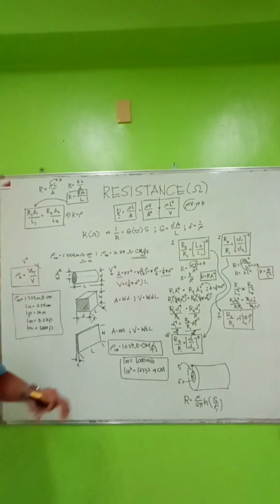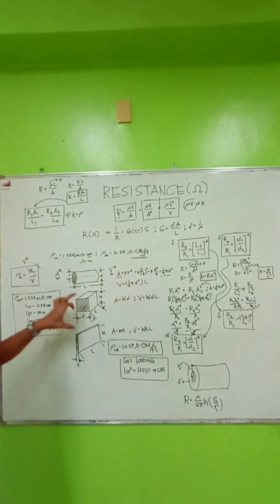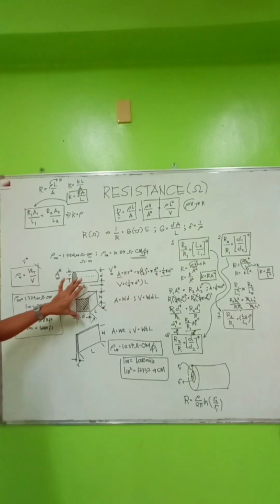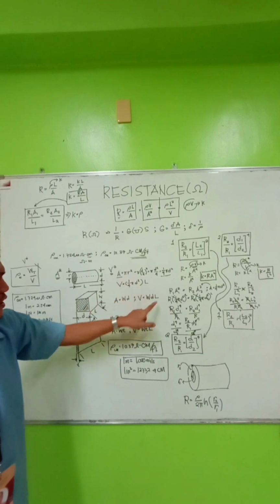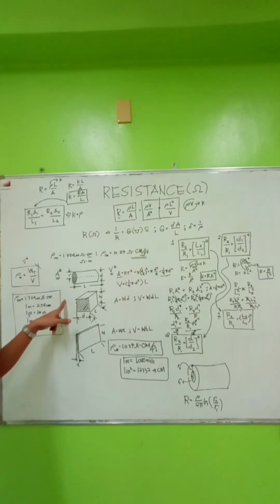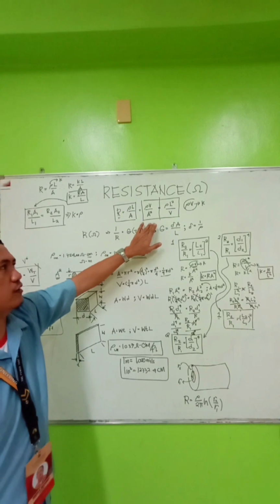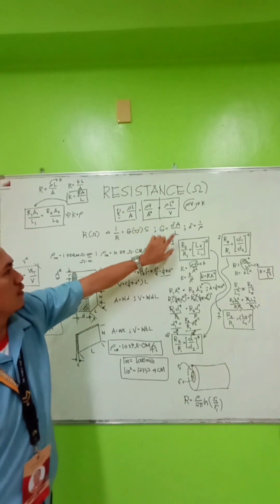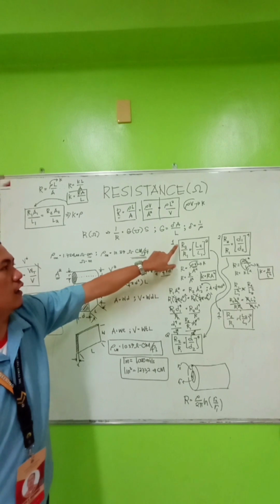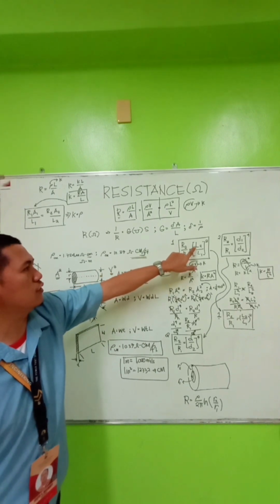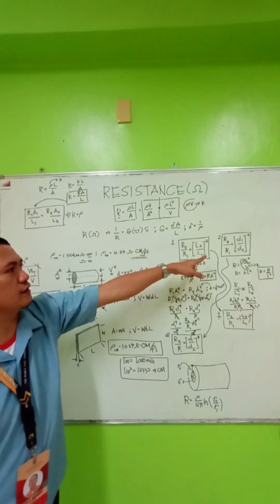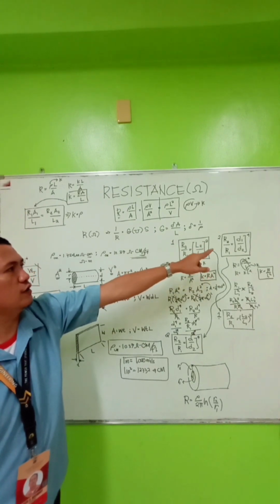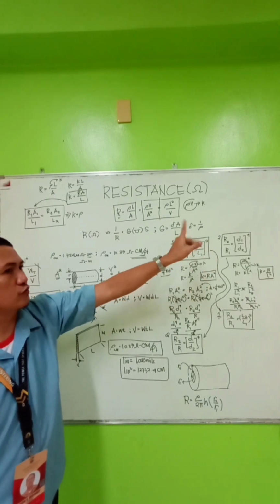So that is the formula for resistance if you are dealing with a cable. Let's recall if you have forgotten anything. You need to deal with the cross-sectional area. If you're looking for volume, take your cross-sectional area multiplied by your length. If you're dealing with a conductor under a drawing process, you can derive the formula: R2 over R1 is equal to length 2 over length 1 squared, or in diameter details, R2 over R1 is equal to D1 over D2 to the 4th power.